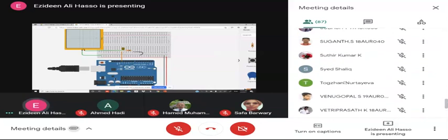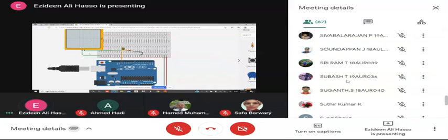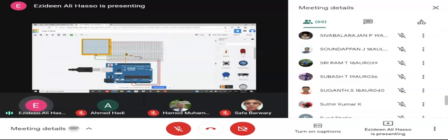This is the oscilloscope. It will show me the signal, okay? We'll run it now and have a look. And this side goes to the LED and monitors what sort of signal the LED is having. The other side, the cathode, goes through this resistance and through this black wire gets connected to the ground, okay? So that's the circuit. It's a very simple circuit. And from the other side, the red and black, I'm supplying to the board.